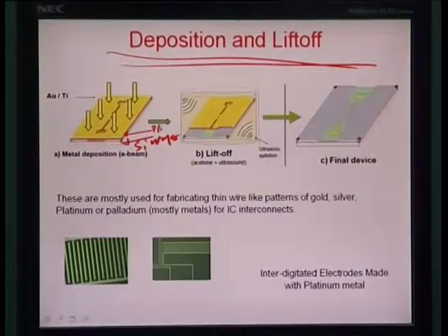Okay, so this is the positive tone photoresist, and a selective feature is etched by photolithography and developing process, and now you are exposing this first to vapors of titanium and then followed by vapors of gold. So, you have to really be careful in this about the interlayer adhesion. If you are depositing something like gold, you may have to use either a titanium or chromium layer for